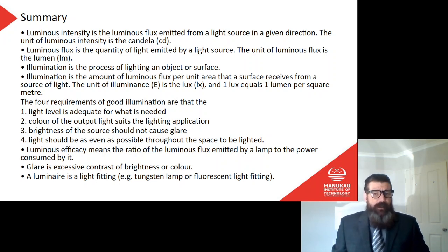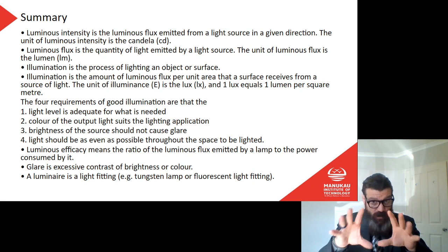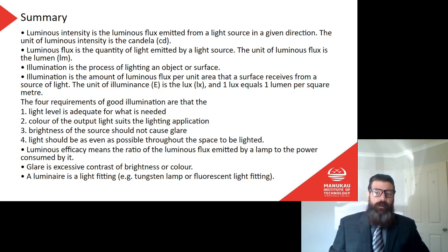So luminous intensity is the luminous flux emitted from a light source in a given direction. The unit of luminous intensity is the candela or candle power. Luminous flux is the quantity of light emitted by a light source, so how much light that thing is putting out. The unit of luminous flux is the lumen.